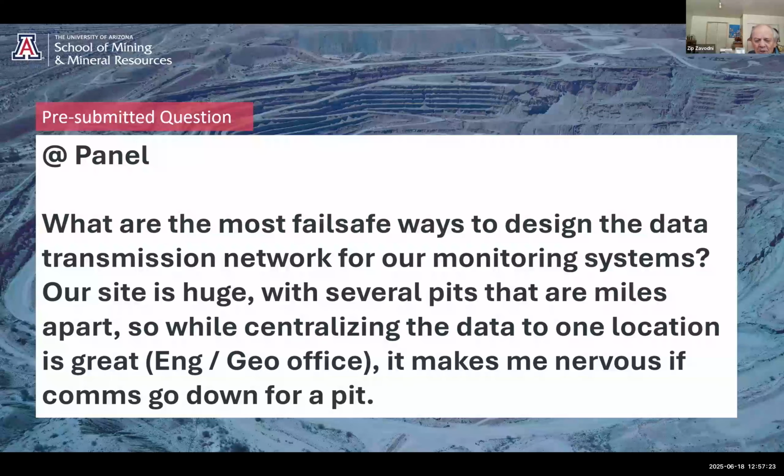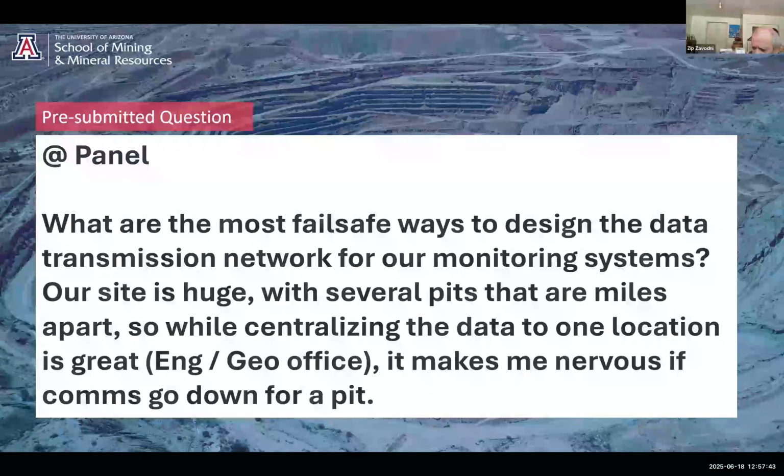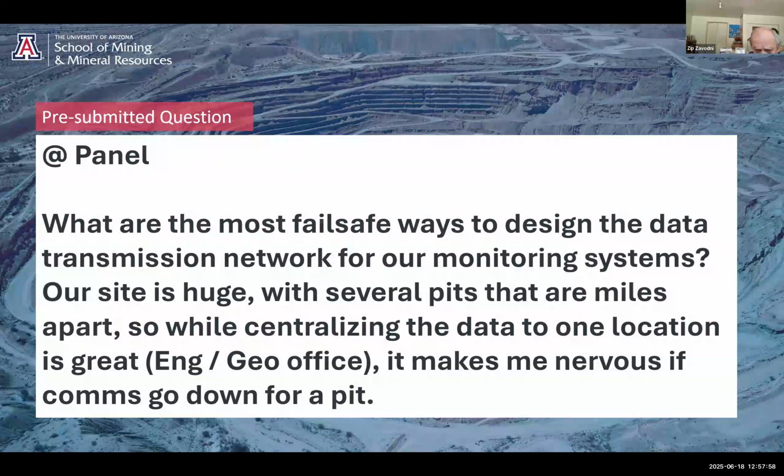Yeah, very, very well put, Charlotte. I think this goes back to the way we used to do it 50 years ago, is we actually had an extensometer across a rear tension crack, and using velocity ratio, normally we used about 1.5 to 2, that would automatically trigger a warning light such that we'd have almost real-time monitoring of that specific part of the pit.